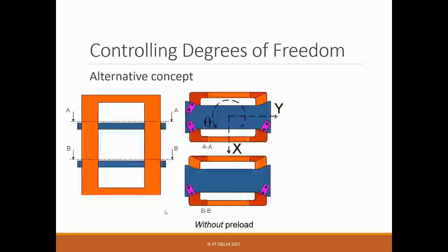How? Just go conceptually. Suppose you take the same problem, the press. What you want to have is 5 constraints. Very simply, suppose you start with this, and you assume that these are point contacts. Assume this is a graphite piece or something, and these are the guides, straight guides.